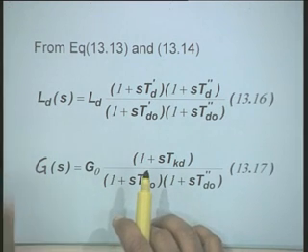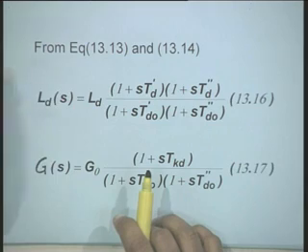That is what we do: this operational inductance we now express in terms of time constants, and these time constants, as we will see, are the standard parameters of the synchronous generator.